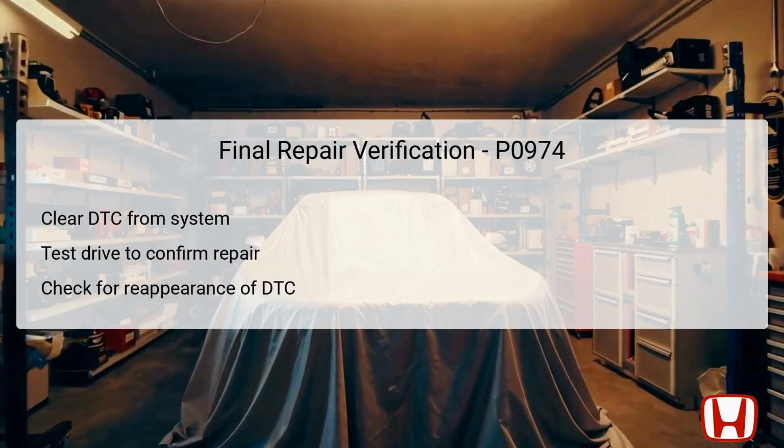After completing the necessary repairs and replacements, it's crucial to perform a final verification to confirm successful repair of DTC P0974. Start by clearing the DTC from the system using the HDS, and then proceed to perform a thorough test drive. During the test drive, observe the vehicle for any symptoms related to shifting issues and ensure the transmission engages properly through all gears, particularly second and fifth.